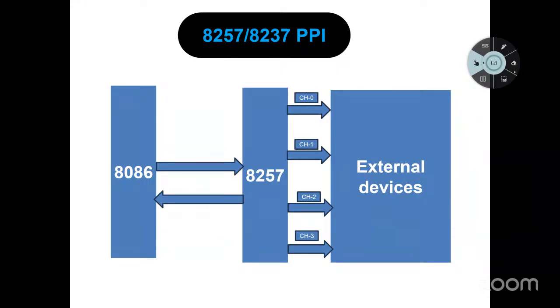You need to draw the circuit, showing how you are sending the signal and how the LEDs of the 7-segment displays are connected. That is the exam point of view. We will meet after.